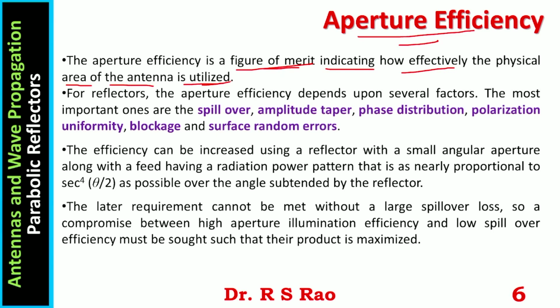For reflectors, aperture efficiency depends upon several factors. The most important ones are spillover, amplitude taper, phase distribution, polarization uniformity, blockage, and surface random errors.